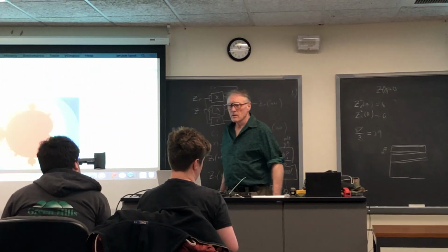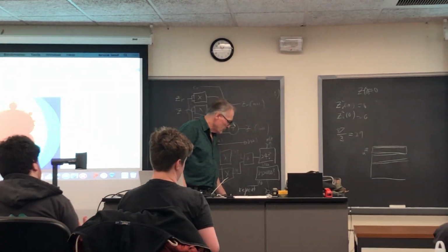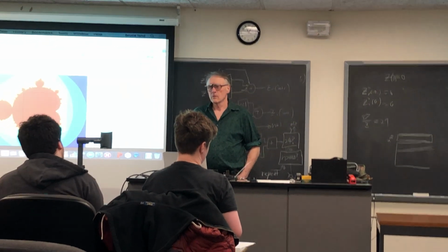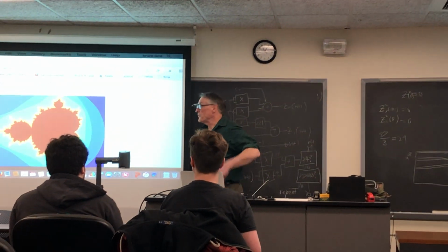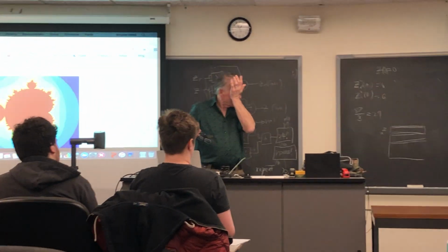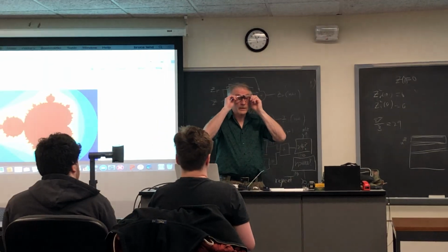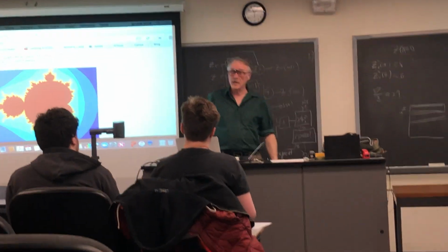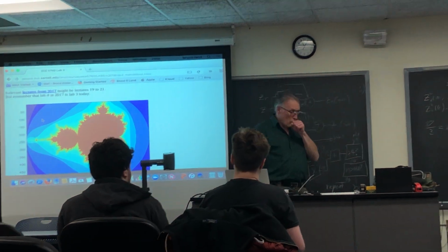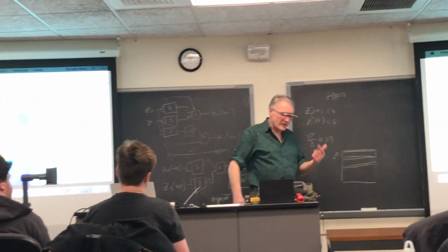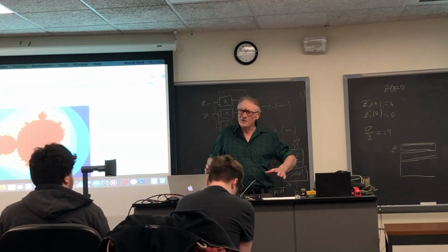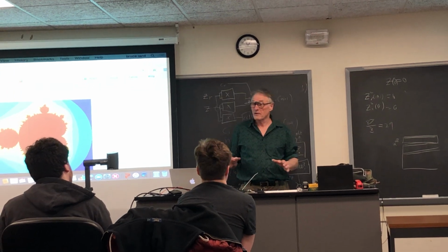For the optimization I saw mentioned, what we've defined is that if in 2 cycles, n and then n plus 1, z has the same value, then it's obviously reached a fixed point and isn't going to change at all. That's also true. If there's no change in the output between 2 cycles, then it's a fixed point and it is guaranteed to stay inside, and so you can just stop iterating. That costs some extra logic, and whether it's worth it or not, I don't know the numbers on that. That would be interesting to simulate and see which way it comes out. I just don't know.